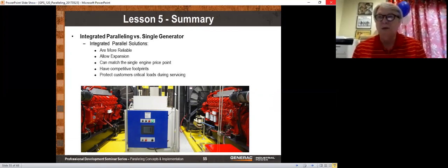And can you do peak shaving? Yeah, absolutely. And we do this all the time. It's becoming very popular that the utility will actually pay you to get off their system during peak times. And if you see peak shaving come up, you can do that. But the simple way to do it is to transfer some of your loads to the generator in order to avoid setting that peak.